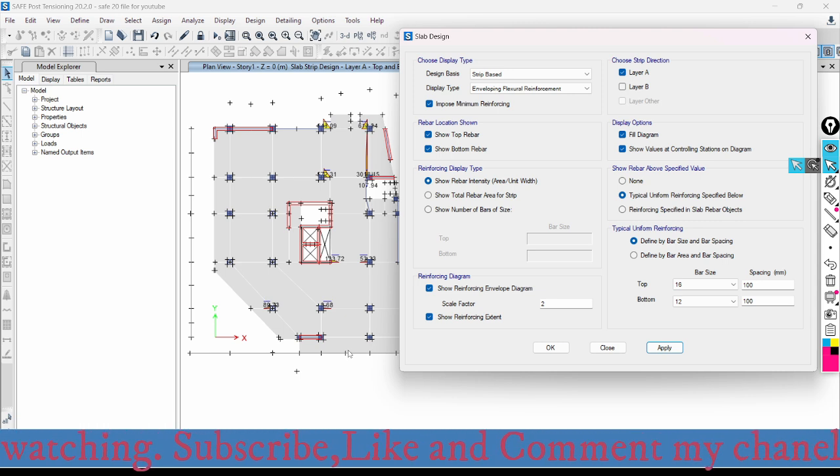But this may not be economical, because at some locations we were using diameter 16 at a spacing of 175 even. And we were using diameter 12 at a spacing of 175 and 150. So it may not be economical. So it is better if we calculate the amount of reinforcement for every strip.